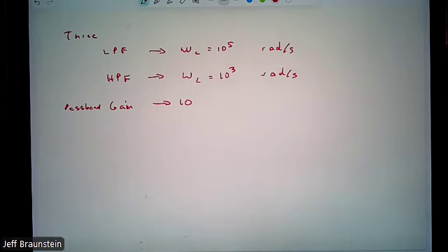They don't need second order circuits, you know. So this one should use that. Because second order, I mean, that was part of the spec, both circuits should be first order. All we're trying to do is change the slope by 20 dB. Second order changes the slope to 40.